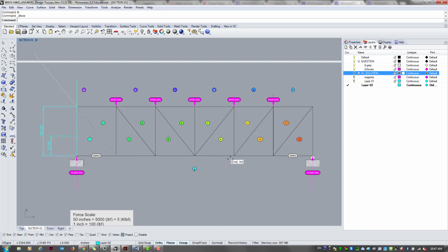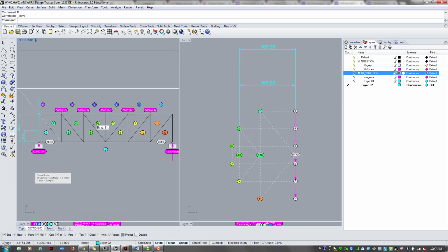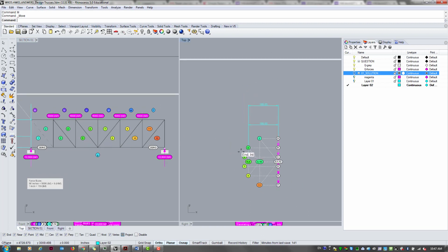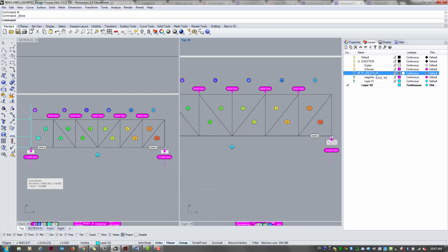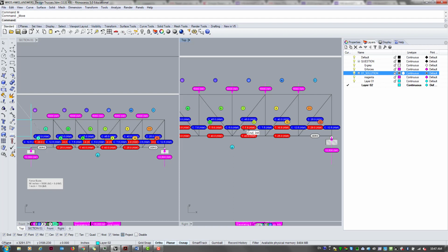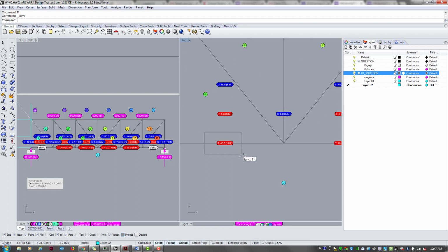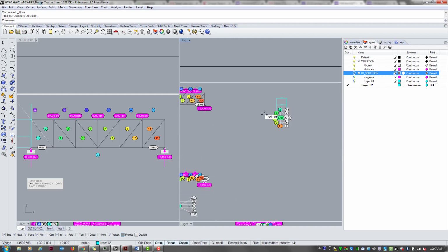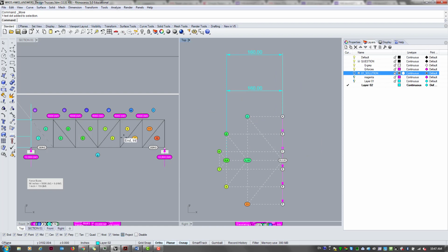But I think this is pretty profound, right? With other methods, you can equally analyze these trusses. But I think the graphic method is the only method where we were able to say, I want to change this internal force in this member to a specific number, and we were able to manipulate the diagram and then dictate what form the truss should have.